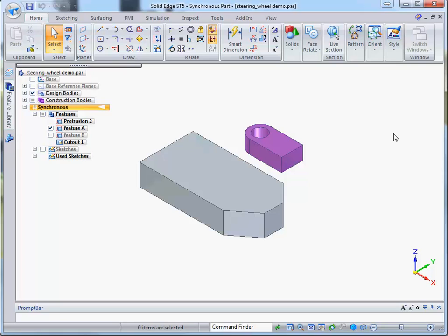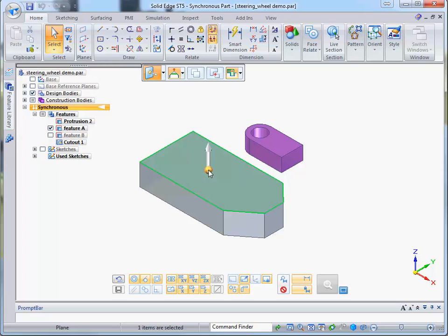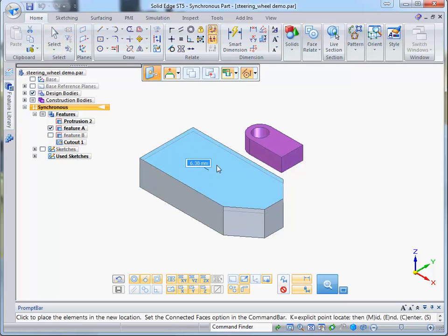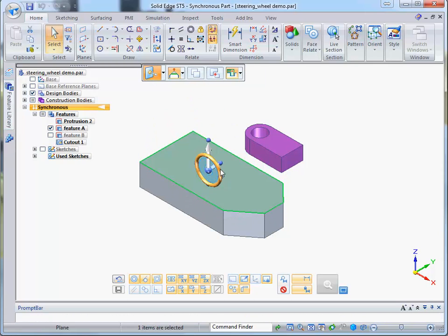I'd just like to show you the main tool of the Siemens Solid Edge synchronous technology, the steering wheel. The steering wheel is the tool we use to modify the faces of solids in the synchronous environment. The way we do that is simply to place our cursor over our face and click, and you'll see how a control arrow appears. I can click on that control arrow and move that face. No playing around with sketches or anything like that.